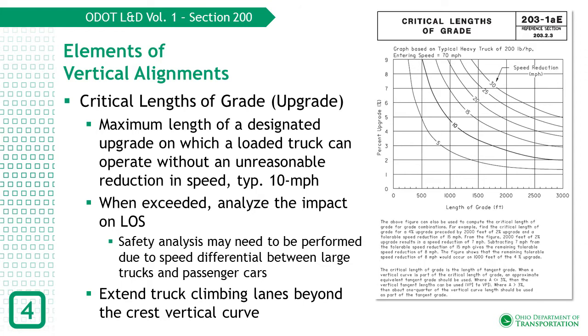Those truck climbing lanes should be extended beyond the vertical curve at the end of the critical uphill grade to maximize their benefit by allowing trucks to regain the reasonable speed threshold to merge into the through lane again. When the length of added lanes needed to preserve the recommended LOS on sections with long grades exceeds 10% of the total distance between major termini, consider constructing a divided multi-lane facility.